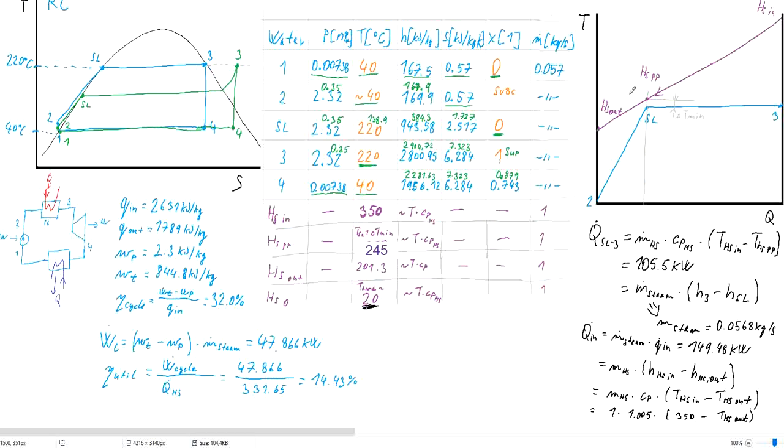So now in the TQ diagram, the green cycle ended up also at a temperature of 220 degrees C, which was over here, but then it had some superheating. Then only took place the evaporation and the heating up from the subcooling. So actually you can already see from this that the transferred heat will be higher.